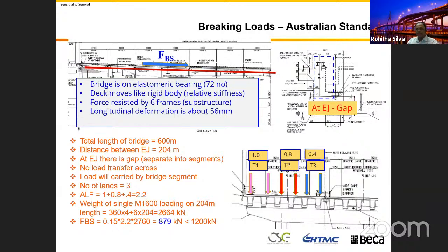Yeah, and this shear stiffness, because of that force transfer across the bridge, that will translate back to substructure. Then substructure will deform, and that will add on to the bridge by another delta amount. Then the total movement of the bridge, not the relative movement, global movement of the bridge will be a little higher because your abutment is a bit stiff compared to the bridge piers. Then you have a little bit higher, couple of millimeters add.